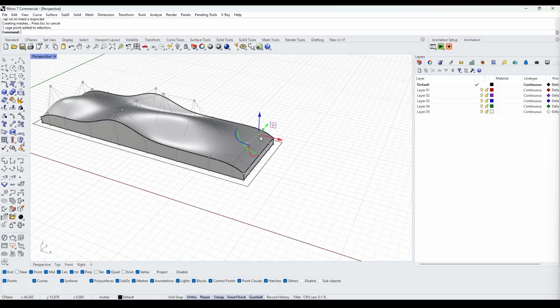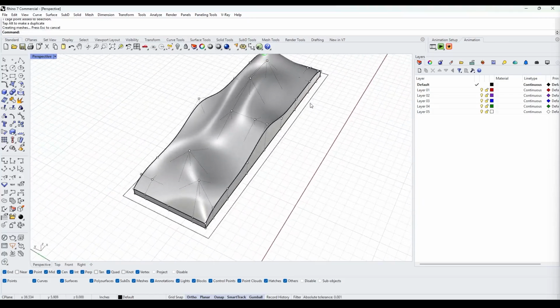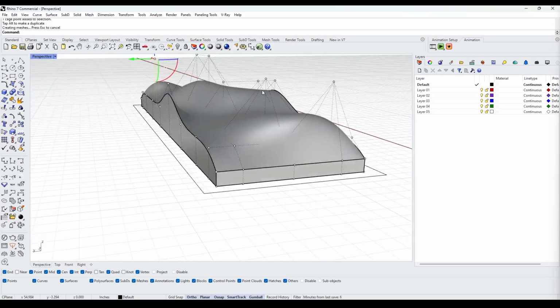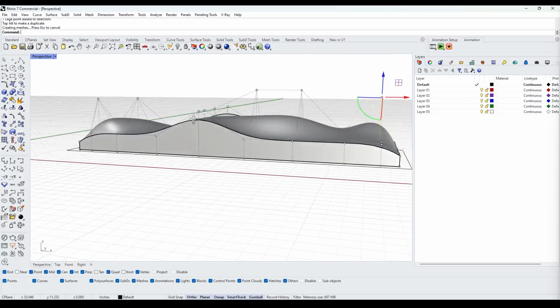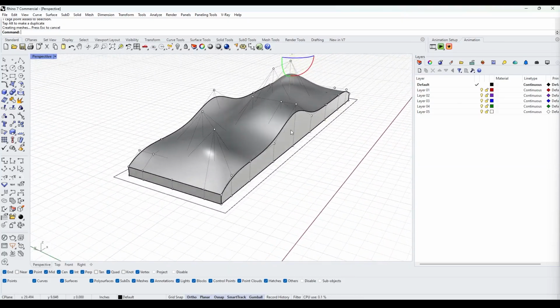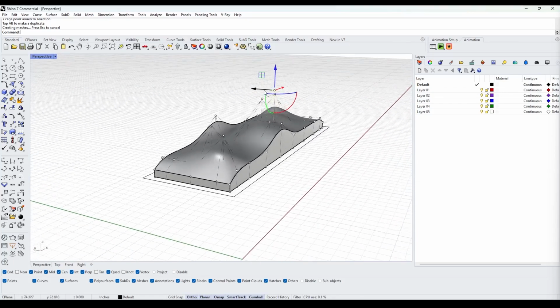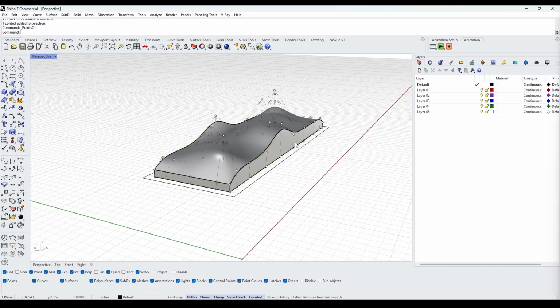And so what cage edit does is it gives you a cage that binds your entire object. Now you can use those control points to move the geometry and create this type of look. We can always change it using those points. So if we select the control point and type in or click on F10, you'll get the points back and you can move them and adjust it this way.